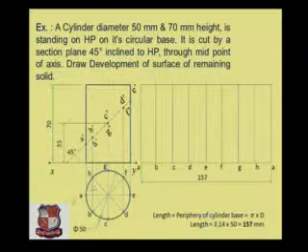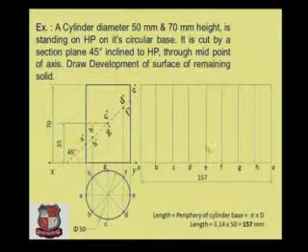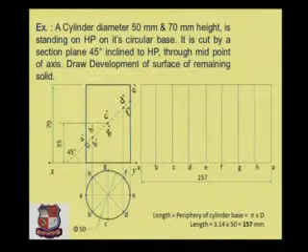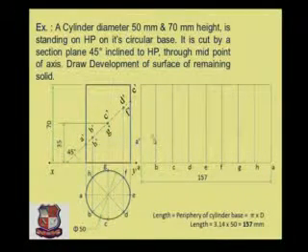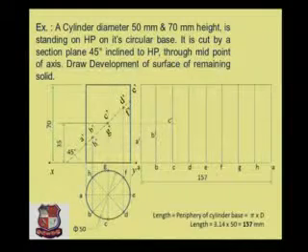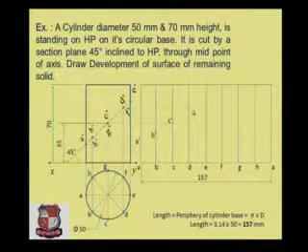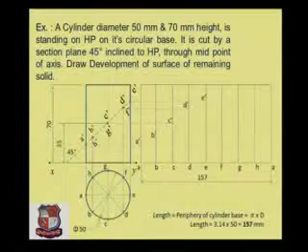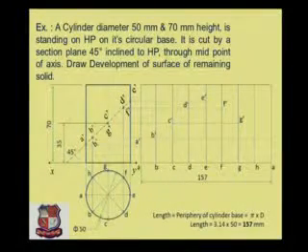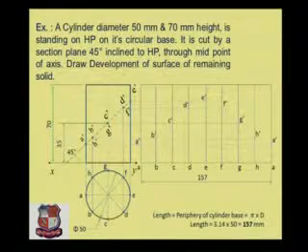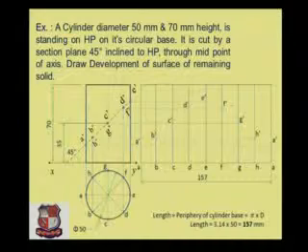These are the names. So we start from here, A, B, C, D, E, F, and so on. After naming these points, take appropriate points from A dash, draw a horizontal line like this, right, which cuts the vertical line from point A at point A dash. From point B dash, draw a horizontal line like this, which cuts over here at some point, that is B dash. Similarly, then this is C dash, then this is D dash, a horizontal line from point D dash, which cuts over here at point D dash. Similarly, E dash point is there, then F dash, then G dash, then H dash, and then back to A dash. So these are the endpoints of this developed solid.